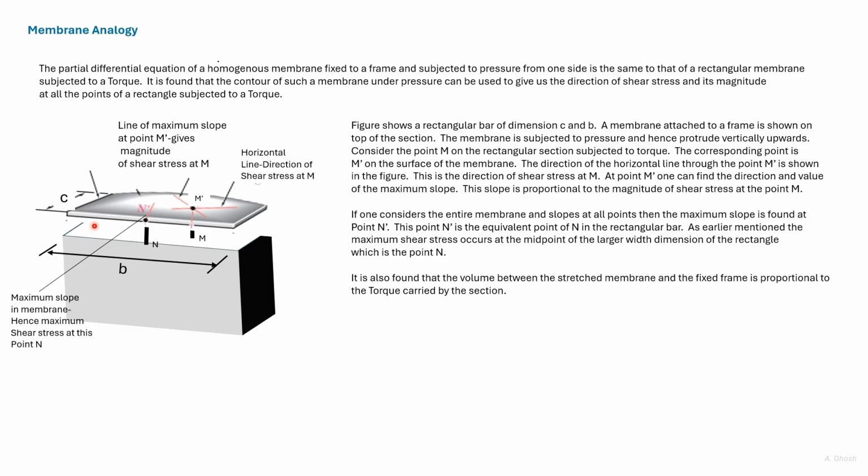For this bloated membrane, we find that the slope at N dash is the maximum slope considering all the points. N dash is the middle of the largest side. This matches with the fact mentioned earlier that the maximum stress for a rectangle subjected to torque is at the middle of the larger side.